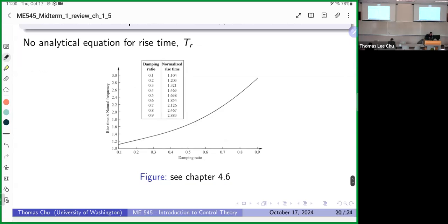One other thing I wanted to note that I don't have on here is that when you're looking at second order systems and you have your poles here, just as a little reminder, the height here is your damped frequency. So this is the imaginary axis. This is the real axis. And then we have our minus zeta omega n.